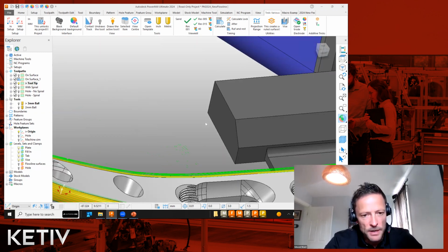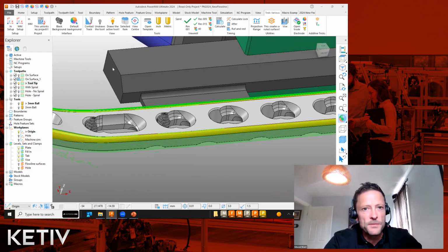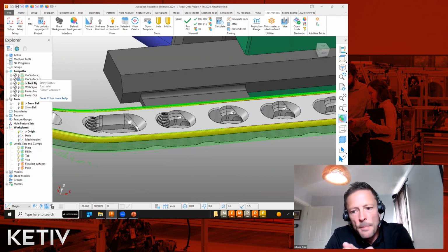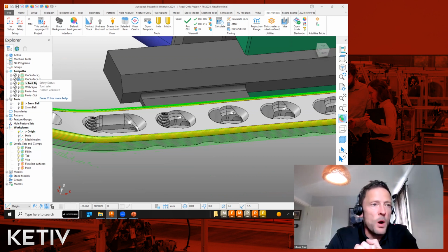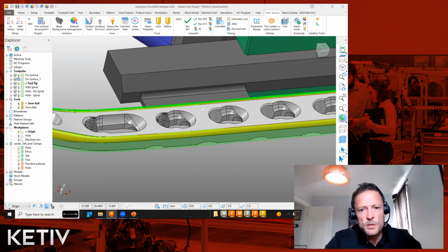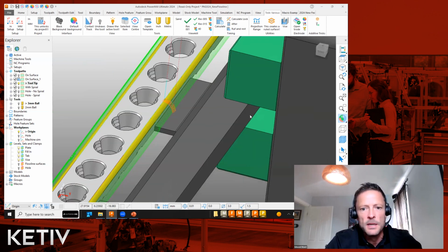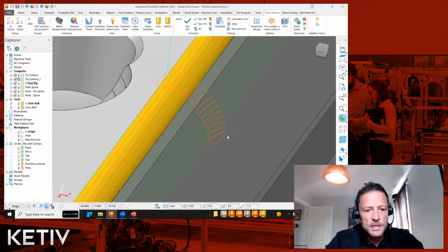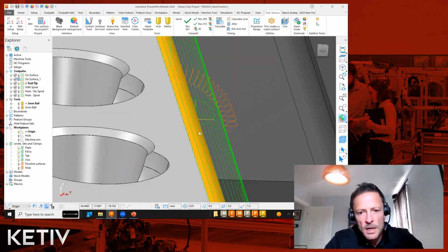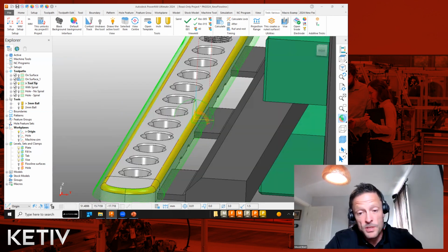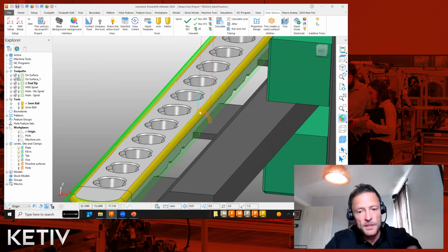But I think the big thing here is, even if I got a good toolpath with the previous version, it did not have the ability to do a spiral kind of toolpath, right? So basically one lead in and one lead out. Now, even though I've got a nice toolpath there, I've got multiple smooth leads and links, but as you probably know, the tool is always going to be deflecting at some point. So anytime that we can keep the tool on the material, it will suffer from less marks that we may have to go and finish afterwards.